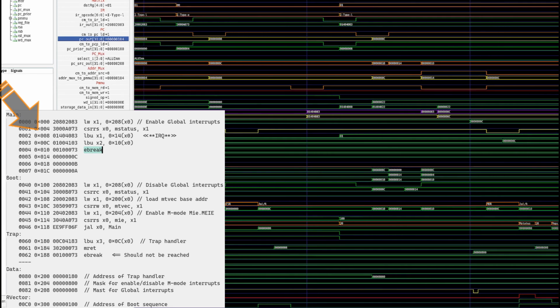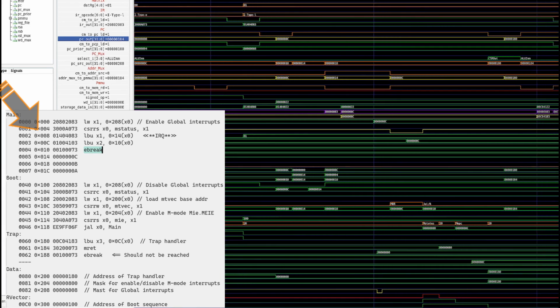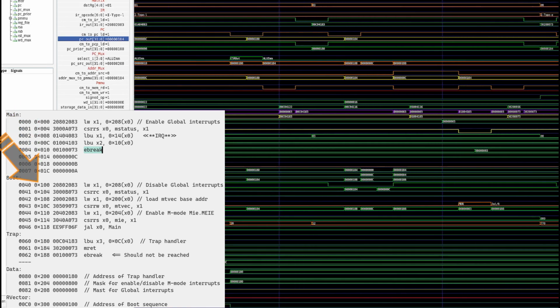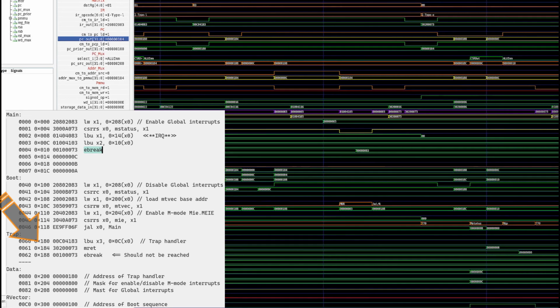And we know that on the next instruction I purposely have put in an interrupt, and right there it is. There's the interrupt, and you can see that it's executing the instruction. As soon as it finishes the instruction on the prefetch stage, it begins the interrupt phase of it, and it jumps to the interrupt handler, and there is the instruction at the top of the trap handler, the C0 instruction. Excellent. Keep moving along.